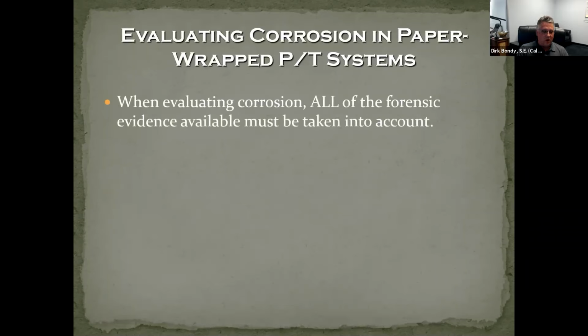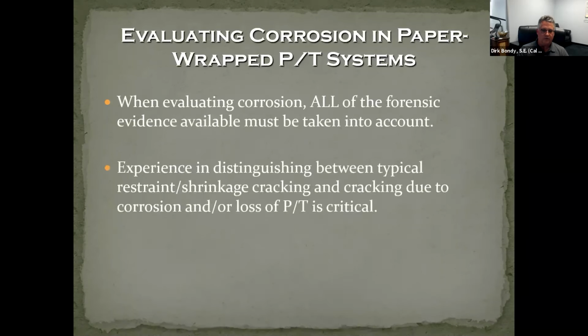So you need to look at all of the evidence. Don't focus on one particular liftoff test giving you all the evidence. You've got to take the whole building forensically into account. Distinguish between the different types of cracks that you're looking at.